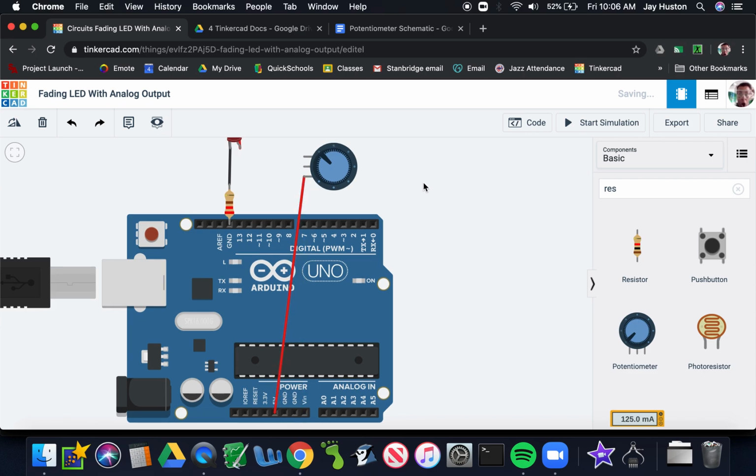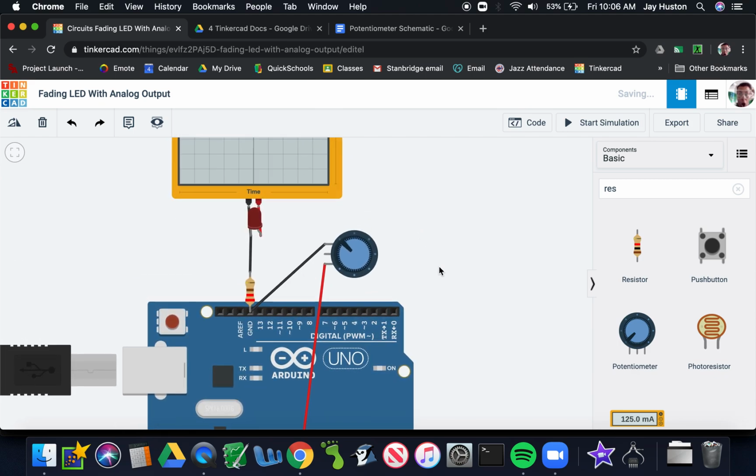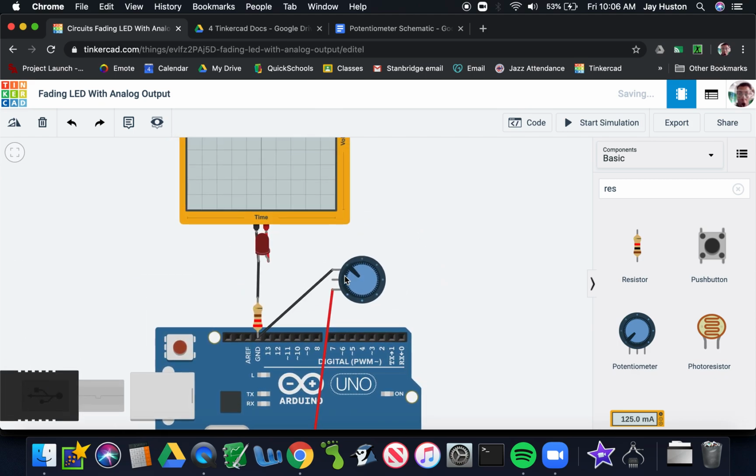So we've powered our potentiometer, and this one here, that is the low volume, that has to go to ground. So this ground is just closer, so I'll use that, but we could, of course, use these pins down here just as well. And so now the power comes into the potentiometer, it goes around the resistive strip, and it leaves, doing absolutely nothing. Now let's make it do stuff. Let's take this and put it right there.